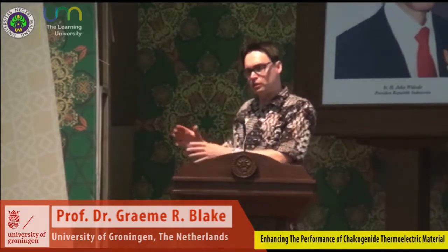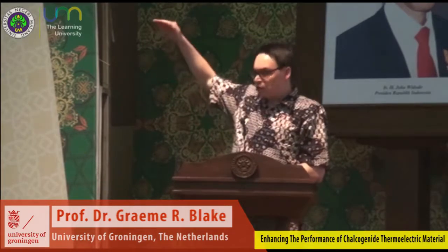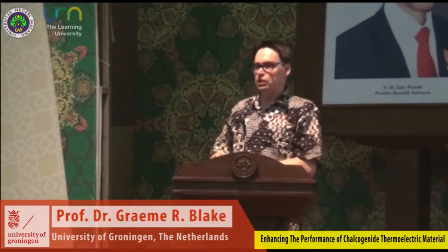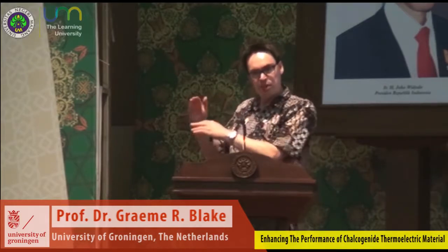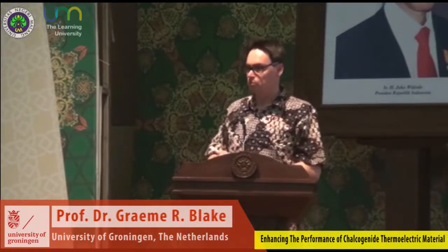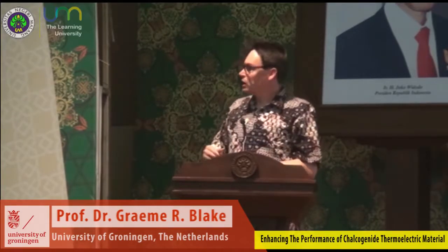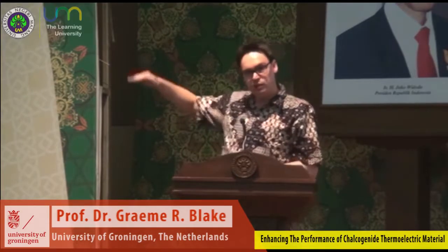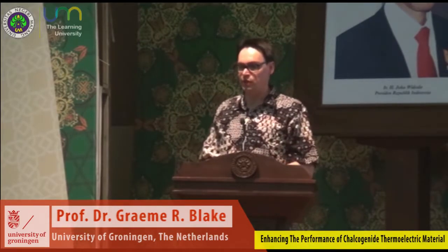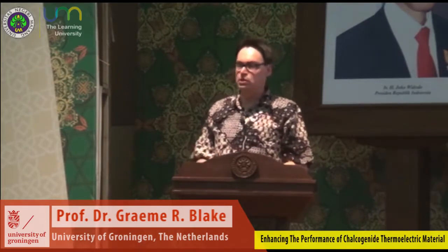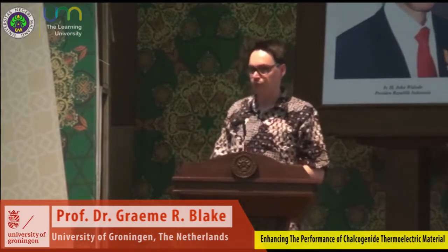So that spontaneously comes out of the TAGS phase when you heat it up. When you heat it up further to above 350 Celsius, the impurity phase redissolves again in the TAGS matrix. It disappears and the material becomes purely cubic. So the operating temperature range in a TAGS thermoelectric module is mostly in this intermediate regime where we have the spontaneous precipitation of the impurity phase. So this is likely helping to lower the thermal conductivity and gives us the good thermoelectric properties. Next, please.